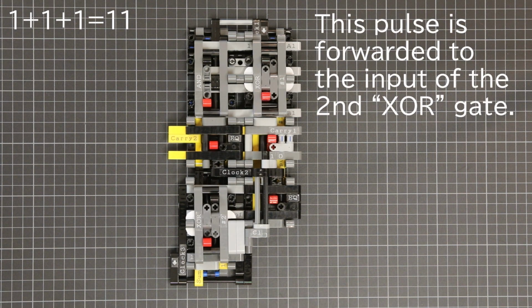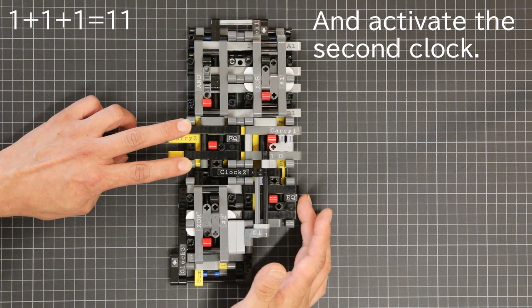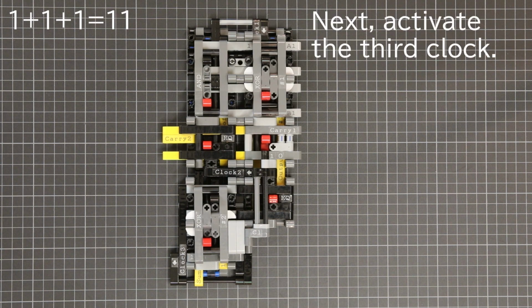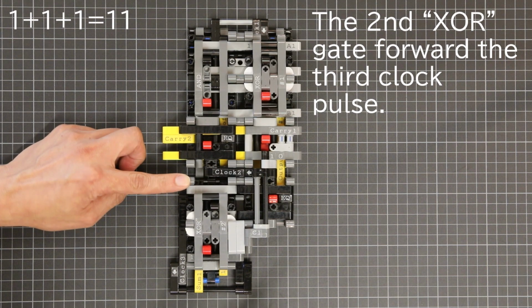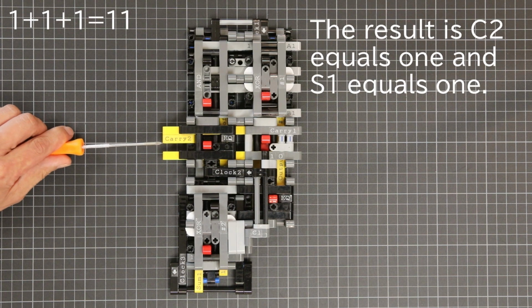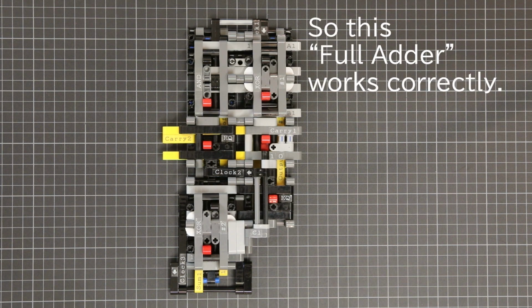This pulse is forwarded to the input of the second XOR gate and activates the second clock. This pulse is forwarded to the output of carry 2. Next, activate the third clock. The second XOR gate forwards the third clock pulse. The result is C2 equals 1 and S1 equals 1. So this full adder works correctly.